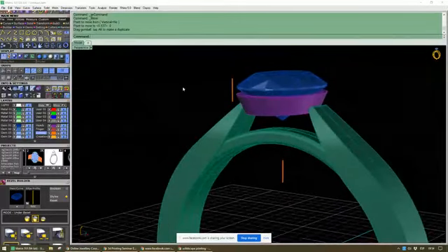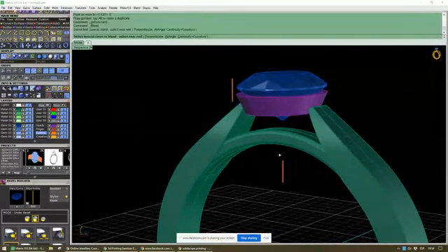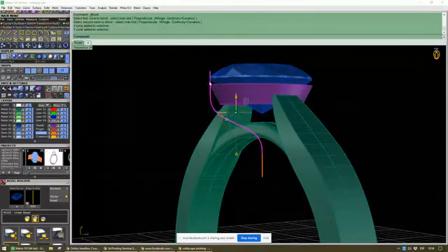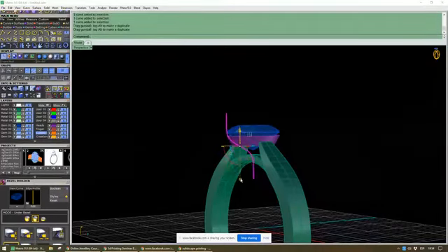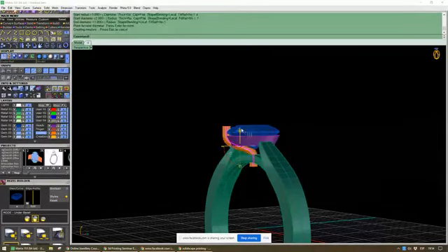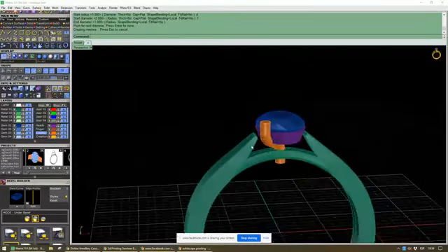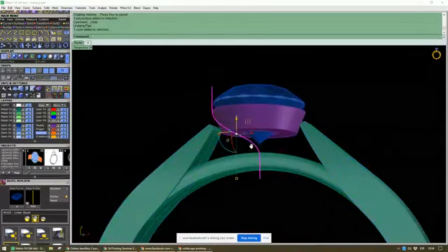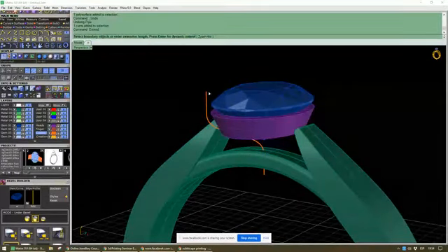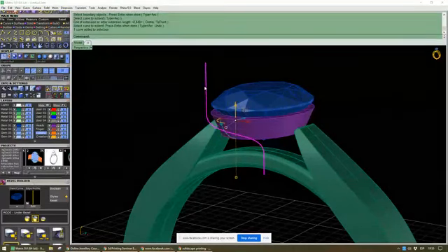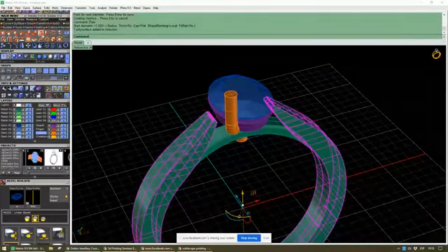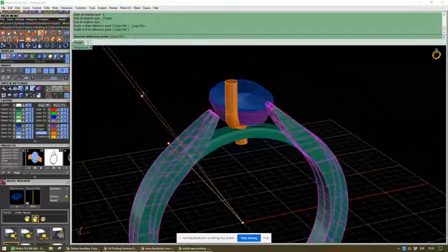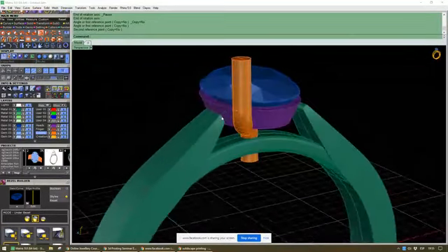And now just with these curves, what you could do is this blend curve. So with this, you have an approximation that would help you to make a claw. Okay. It's something. Probably make it a bit longer, so I would extend the curve on the top. And I want this to be touching the under bezel, so I'm going to change it again. So it's more like this.